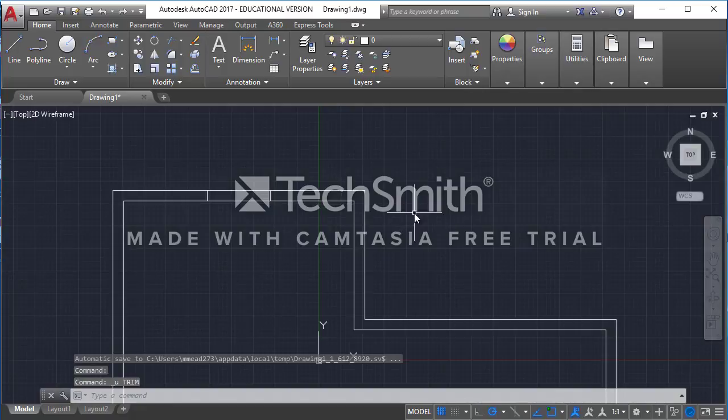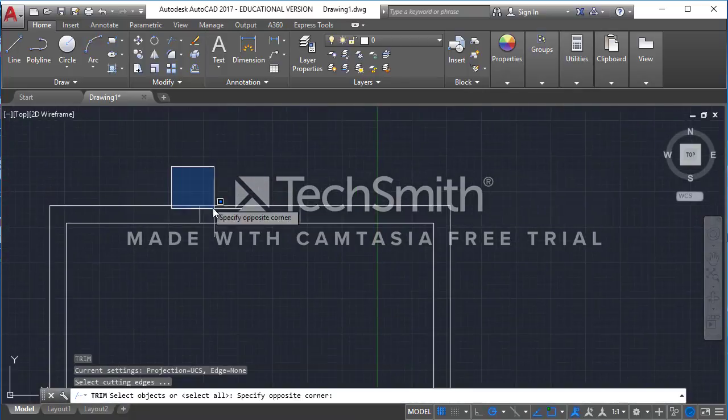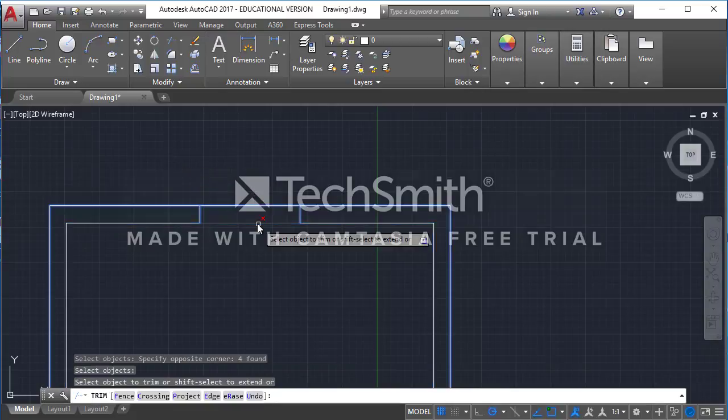Okay, so I'm going to do that one more time. I'm going to type in TR for trim. I'm going to select all of the objects that I want to trim from. So I've selected all of these lines right here. I'm now going to hit enter, and it tells me to select the objects that I want to trim. Notice that when I hover my mouse over this line, it's telling me that it's going to trim this line. Notice that it does not go any further beyond those corners.